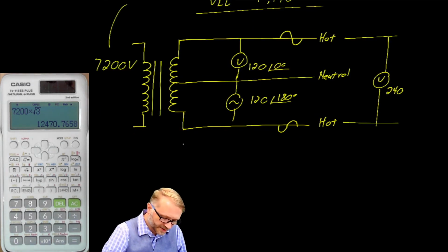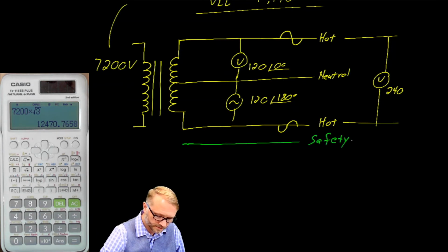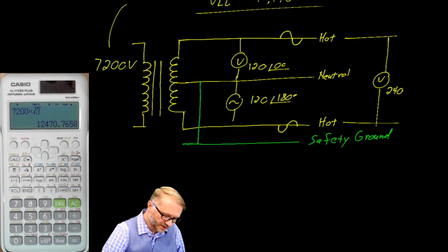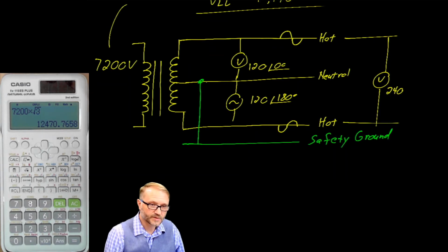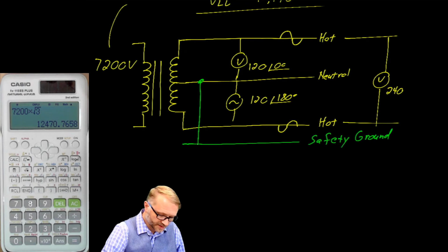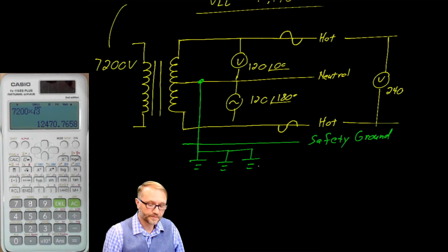There's another wire in your house known as the safety ground. Inside the breaker panel, you'll find that the safety ground is connected to the neutral. You'll also see a few wires leaving. They go to ground electrodes, typically 2, sometimes more, depending on the code for your area.